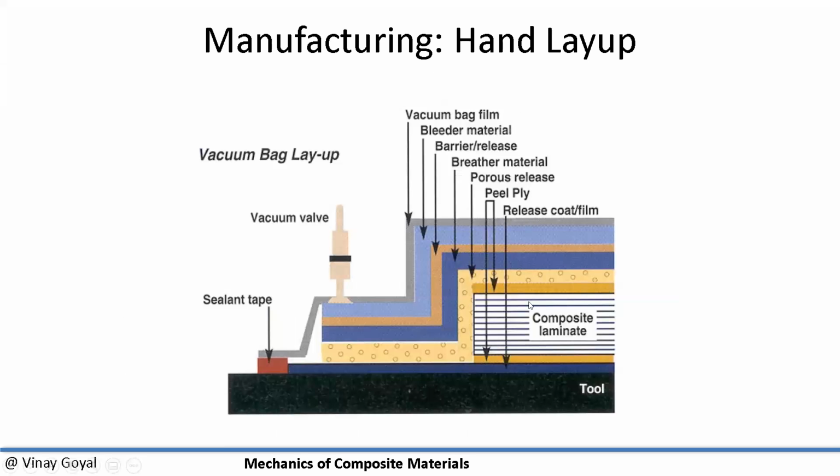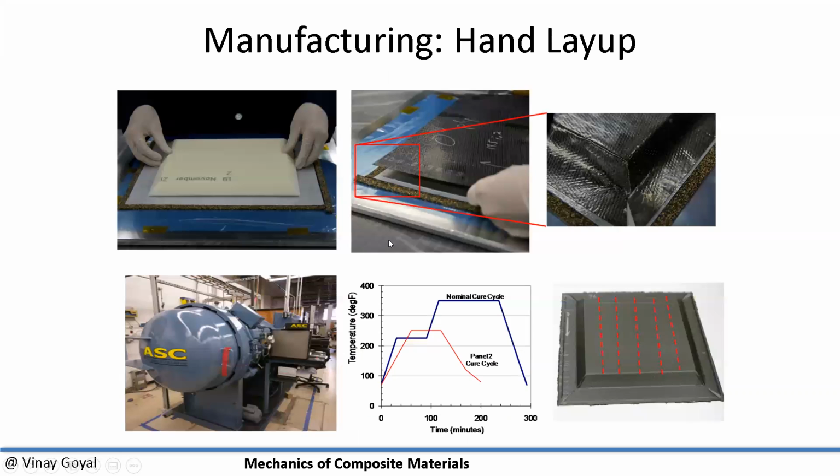And then here's a zoomed in view of the things we discussed. So this is more of a summary. This is laying up of composites. You can see here foam structures getting put on top of a face sheet. And on top of the face sheet, there's a film adhesive. I don't know if you can see the white part, that's an adhesive.